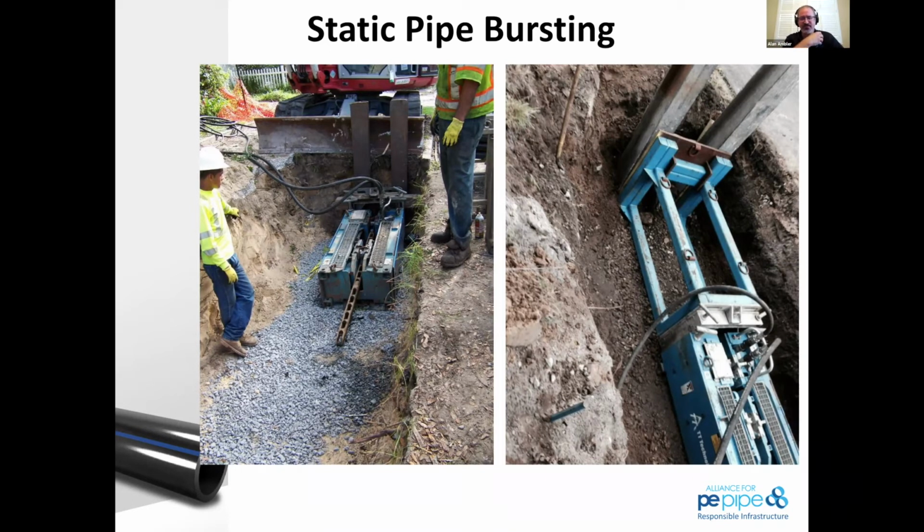We had a question just recently about any concern to use this method for deep burial, and we'll talk a little bit more about it as well. Yes, you can certainly pipe burst very, very deep installations, and you need to take some consideration for the friction forces that are going to be created along that run from the weight of the soil column on it. But typically we just jack up the tonnage of the equipment as we go through that and make sure that those excavations are properly shored as it moves through.